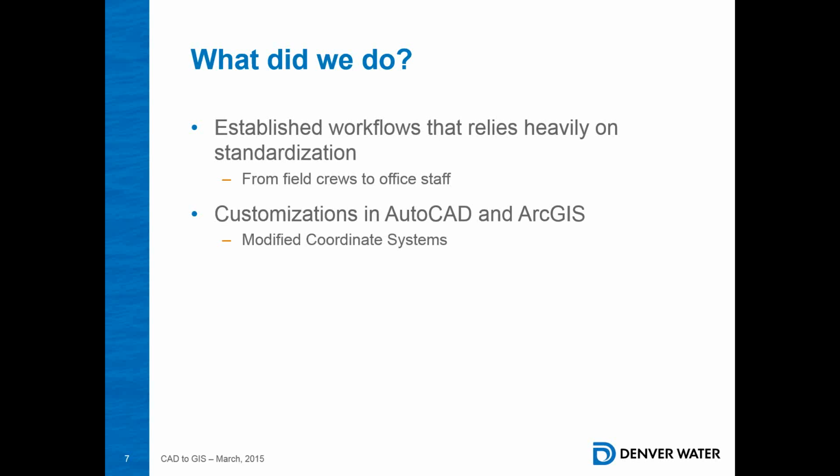First of all, by doing it inside of CAD and inside of the map tools, it allowed a true translation in a GIS atmosphere of the two coordinate systems, which means now I can input GIS data, like Sandy's talking about. I can bring GIS data directly into the engineering data and the survey data without having to worry about things shooting off into the wrong direction or, heaven forbid, eyeballing things. The other thing that it allowed is because they did this inside of AutoCAD Map, they were able to export that coordinate system as a PRJ file. And that means they could import it into their GIS department, import it into all their data collection equipment, and everybody's working on the same coordinate system.